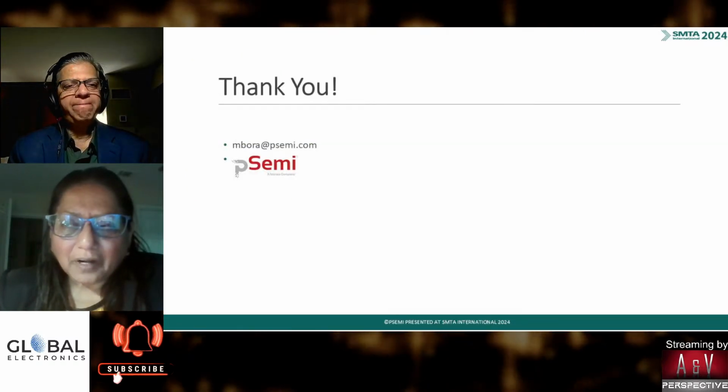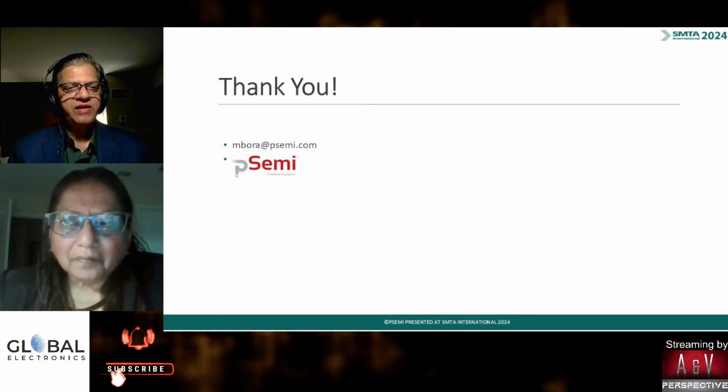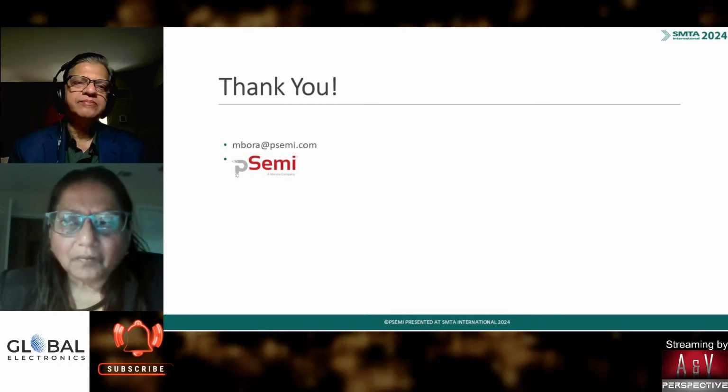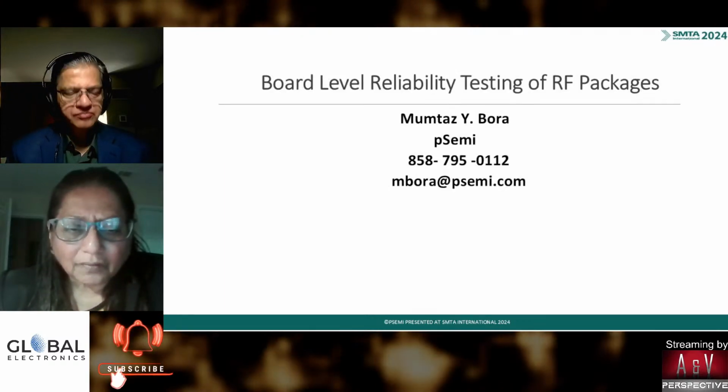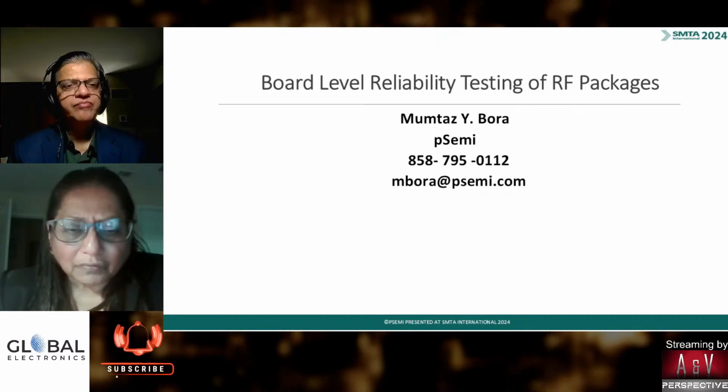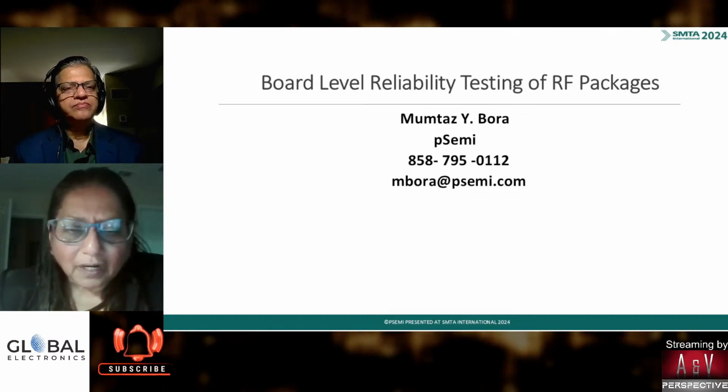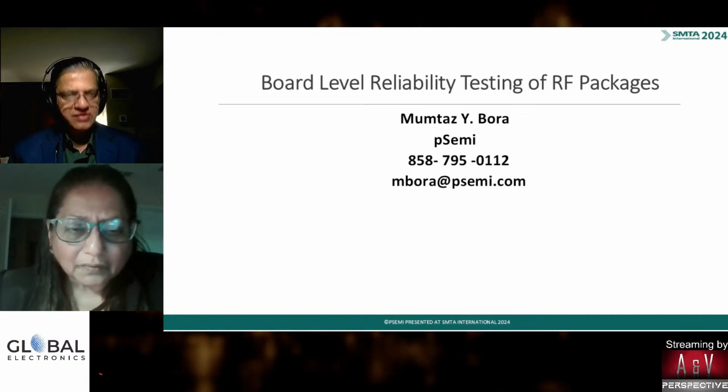So what I wanted to mention was board level reliability testing was done for certain applications like Hi-Rel, space, defense. In some of those areas we had to do it, but we were not doing it so much in consumer products. Now we are initiating that. Based on the learning in the industry, they think that by doing board level reliability testing, they can get a better perspective of how packages will survive in the field.